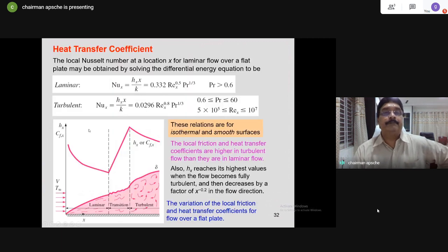Okay. So heat transfer coefficients for laminar and turbulent, you have different equations. And again, these heat transfer coefficient equations are available in your data books. I think all of you who are pursuing heat transfer are fully aware of these data books. For different Prandtl numbers, you find different equations, for different ranges of these, limiting values also there. So you cannot apply these equations for Prandtl numbers less than 0.6. You can apply only for Prandtl numbers greater than 0.6.